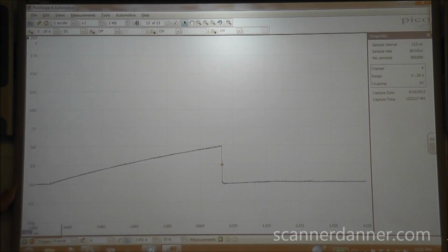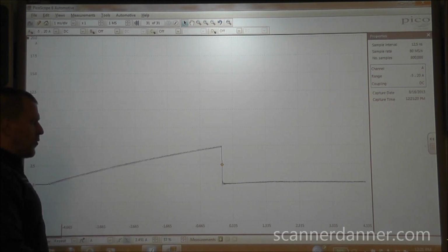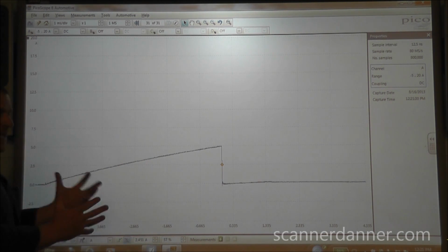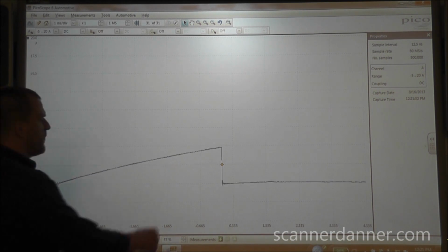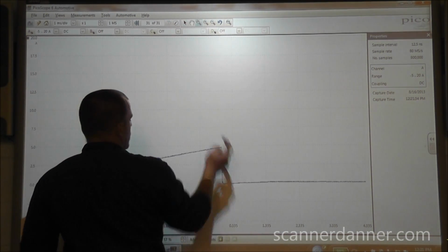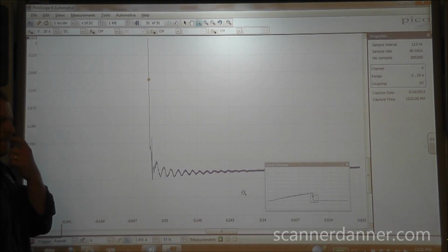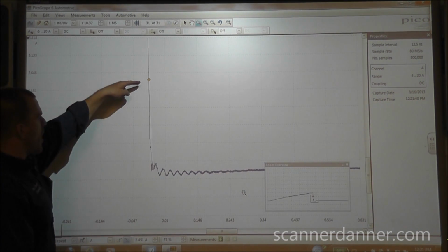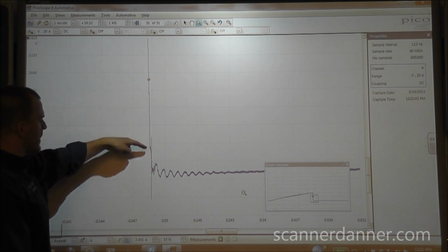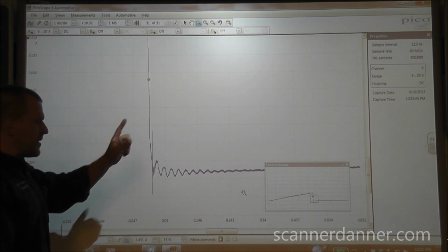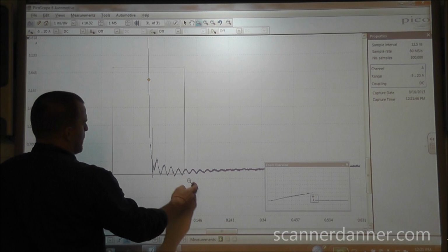So a lot of you have asked me in the past, what do you want to trigger at? Like, what level do you want to choose? Well, there's really kind of a rule that I follow, and that rule is, where is a clean line? And if we would zoom in this area, you're going to see that this isn't so clean, is it? So I would not want this trigger down into this level. The reason why, let's go a little bit further,